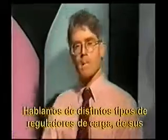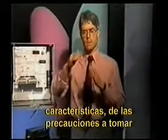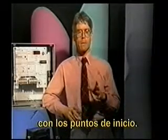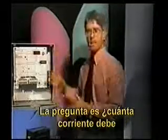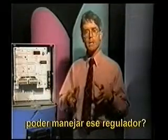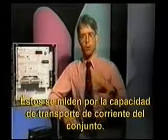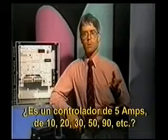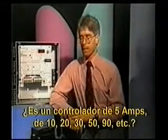We talked about different types of charge regulators, some of the different features involved, some of the set point features that you have to be careful about. Question comes to mind, how big of a regulator do I need? I don't mean physically, how big does it have to be, but how much current should it be designed to handle? Regulators are measured by their array current carrying capacity. Is it a 5 amp controller, 10 amp, 20, 30, 50, 90, and so on?